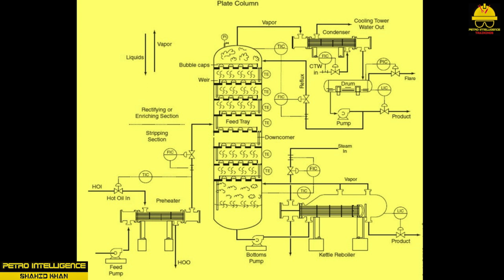As vaporization occurs, the lighter components of the mixture move up the tower and are distributed on the various trays. The lightest component goes out the top of the tower in a vapor state and is passed over the cooling coils of a shell and tube condenser. As the hot vapor comes into contact with the coils, it condenses and is collected in the overhead accumulator. Part of this product is sent to storage while the rest is returned to the tower as reflux.